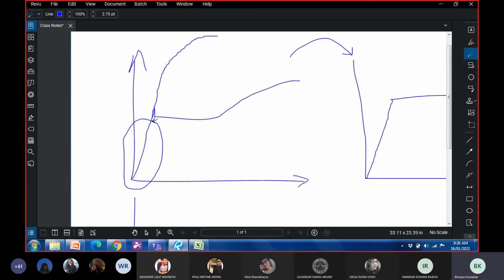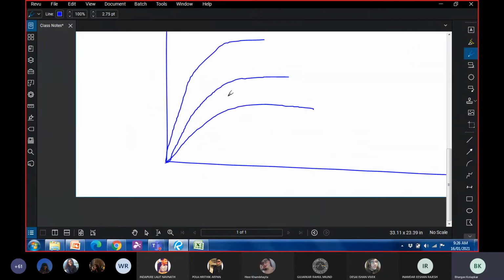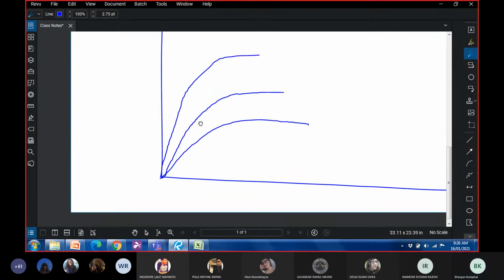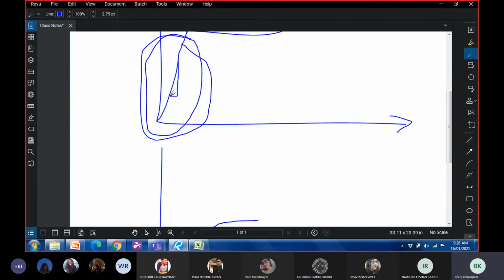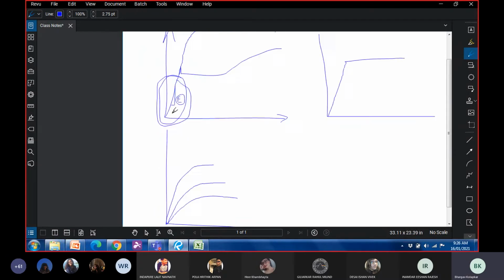It is not like steel, wherein, irrespective of what the grade is, the curve still remains the same in the linear elastic portion. So because of this, now this particular thing is a measure of modulus of elasticity. And therefore, we have the same modulus of elasticity of steel irrespective of what the grade is.